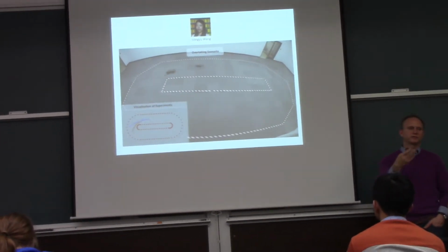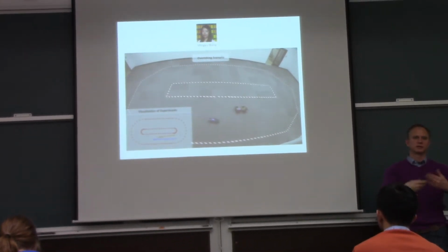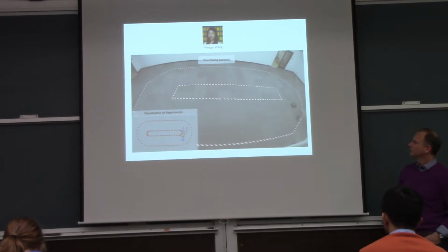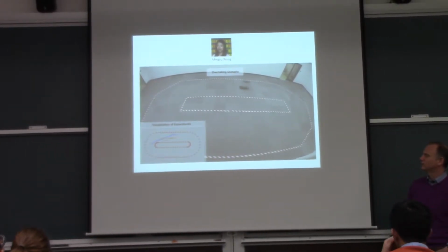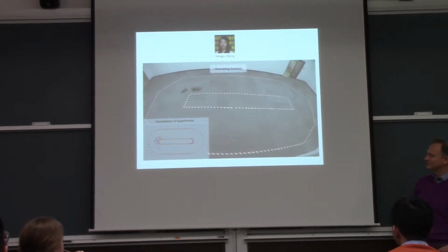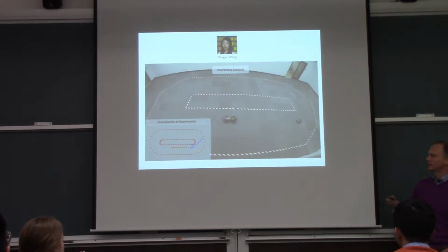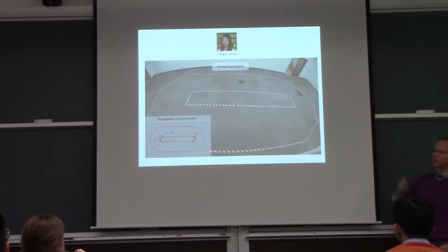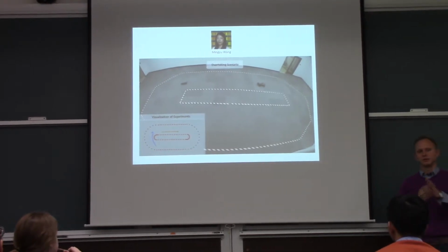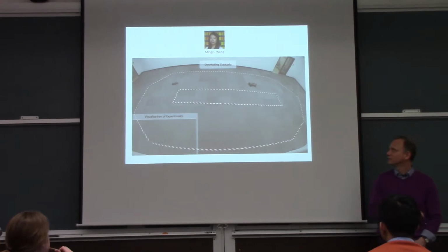The ego robot plans for himself, and then for his opponent, and then for himself, iterating until a convergence, and then you take one step. And so here the big car is slow, the small car is fast, and also the big car here was using a dumb planning method that was not our game theoretic planner. And the small car was using the game theoretic planner, and you can see that the small car is able to find an opportunity to pass the big car.